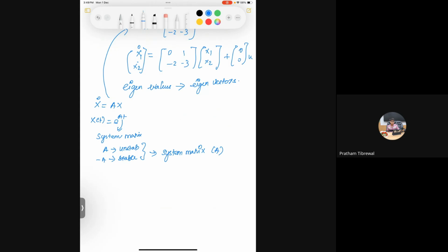In the transfer function it is where the poles are, or how the exponential term looks in the time domain representation. The same system matrix, how can we get it from this A? This is also a system matrix in state space representation, right? So how can we relate this to eigenvalues? The common thing between this state matrix and the solution to x dot equal to Ax is the eigenvalue.